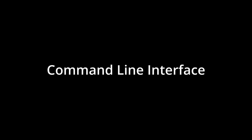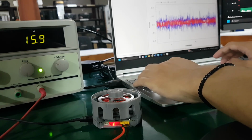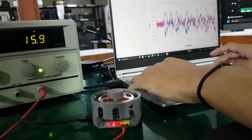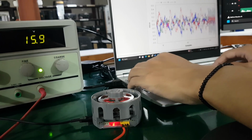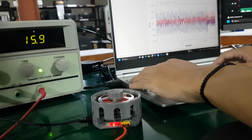Through the CLI, we can interact bidirectionally with a microcontroller. Not only can we receive data for plotting, but we can also send commands to perform parameter tuning, such as changing the values of KP, KI, KD, switching motor control modes, and various other functions.